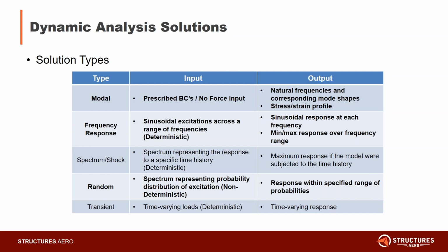There's no force input, and you're calculating the natural frequencies of a structure. Frequency response, again, is typically where your input is going to be some sinusoidal excitation across a range of frequencies. And it's a deterministic analysis. Your response with this is going to give you a min and max response over a frequency range.